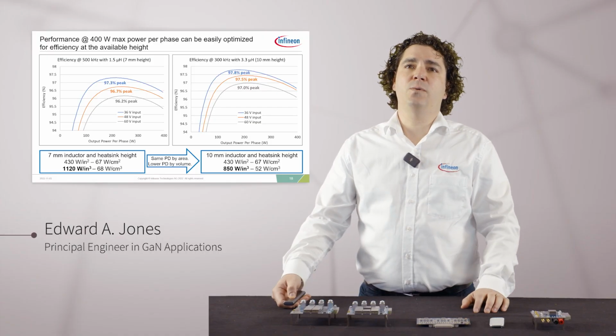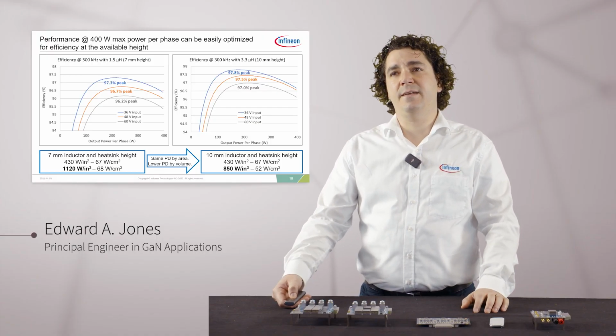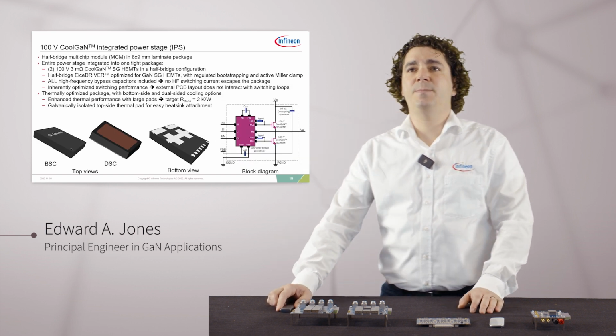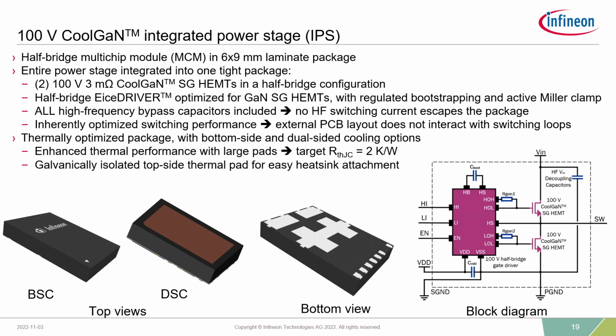And there's an added value of scaling in terms of phases instead of scaling in terms of parallel devices. It allows us to use integrated power stages. Integrated GaN half bridges are not so easy to parallel because they have separate drivers, and paralleling drivers is difficult. You have to deal with propagation delay tolerances. But if you're paralleling phases, then each phase can have a fully integrated power stage like this guy here.